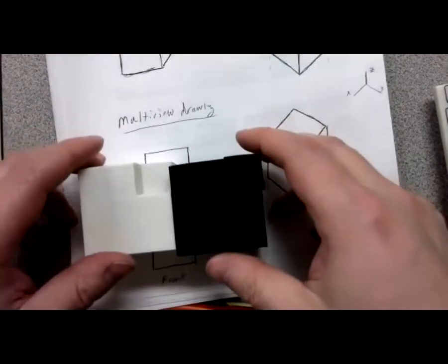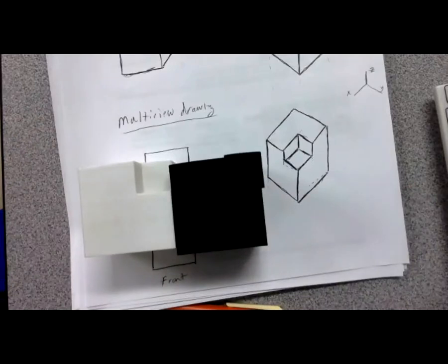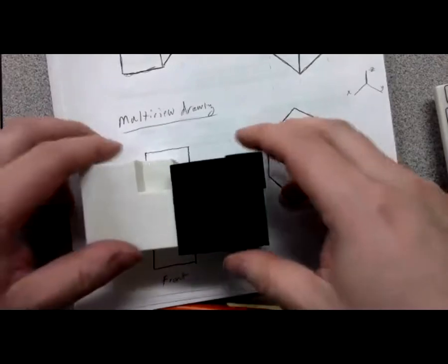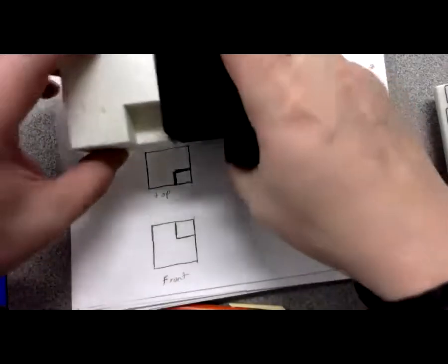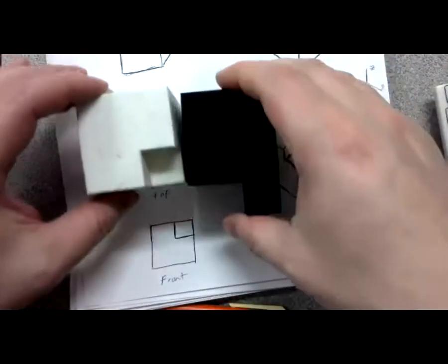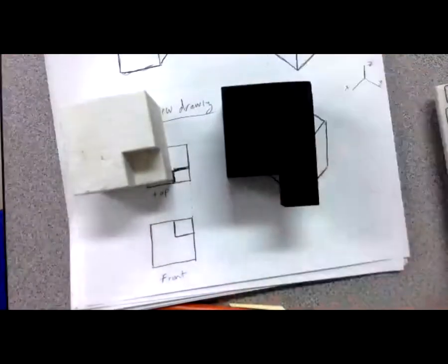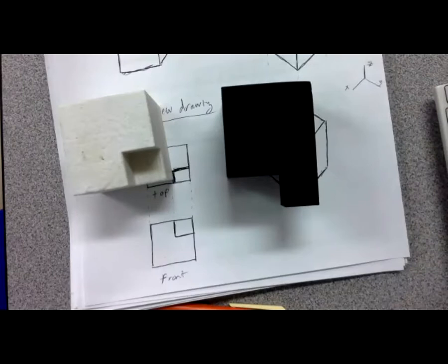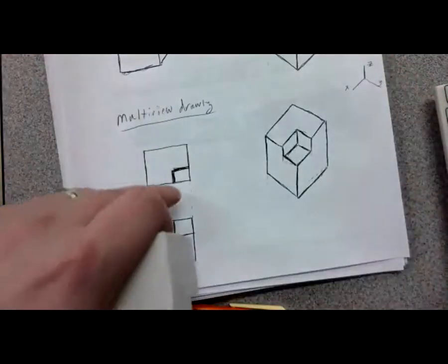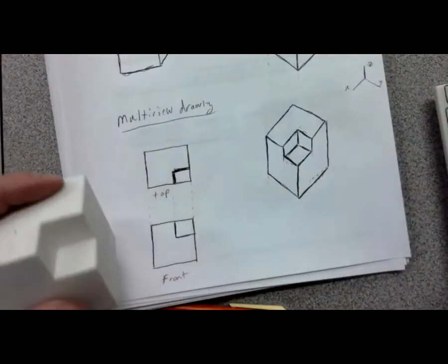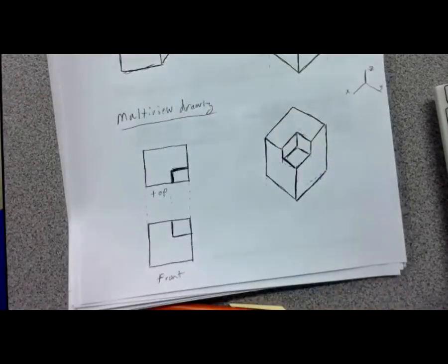But you can see when I look at the top projection, you can tell which is which. You can see the obvious difference in the top projections of the two. So that's the reason the top projection alone tells us, well, I'm looking at this, not this. I can't tell that from the front. I need another view to tell me that for sure.